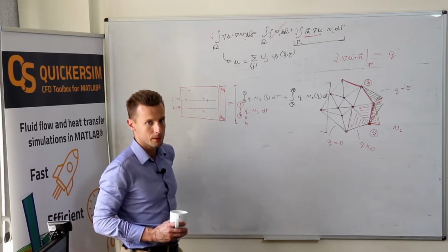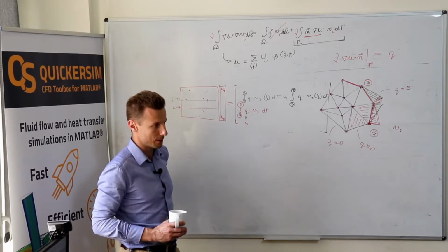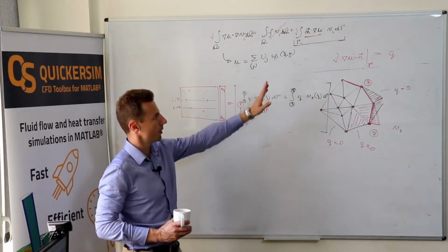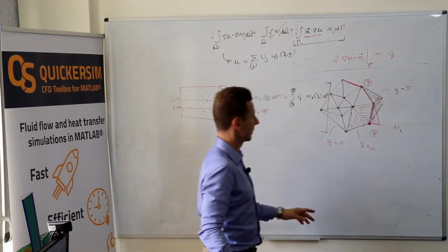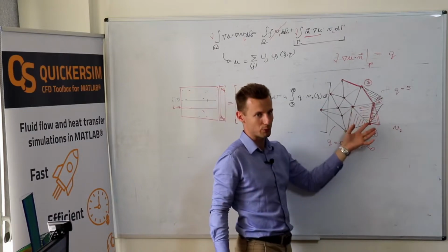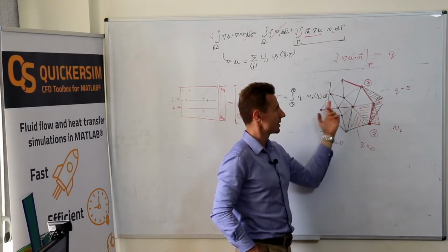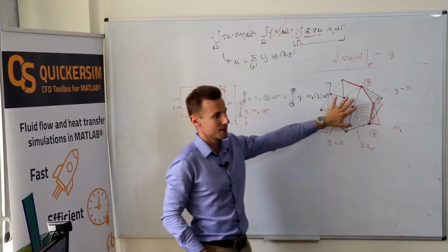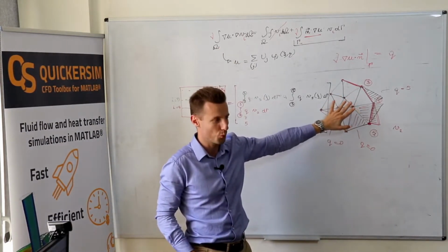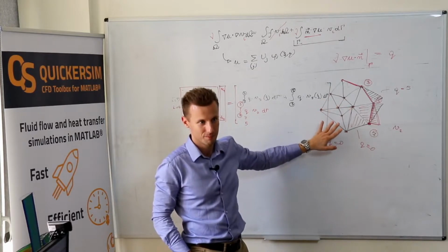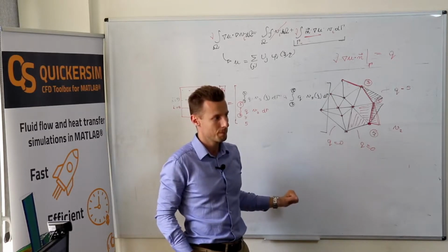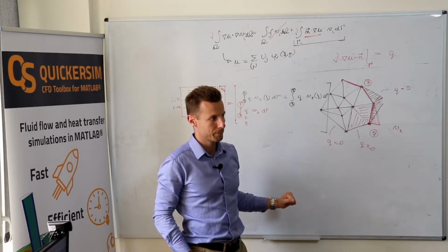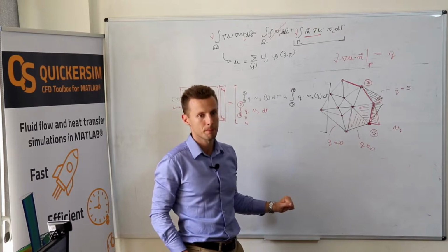Okay? So with the Neumann boundary conditions, it's pretty simple. If you've got 0 Neumann condition, well, you don't do anything. A physical remark, that was a nice example to show you how to implement Neumann boundary condition. For this steady state case, such a set of Neumann boundary conditions wouldn't work. You know why? Because this is without mass matrix, it will be equivalent to pumping energy into the system to infinity.